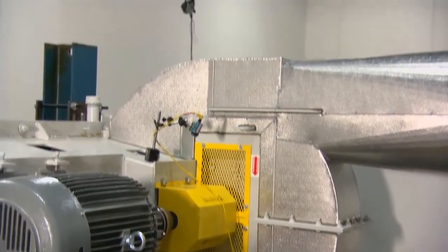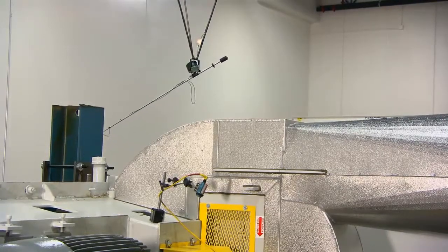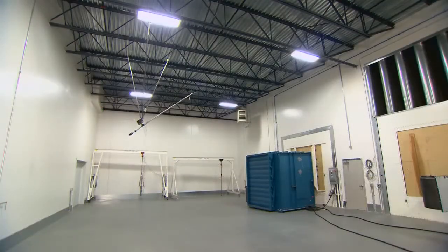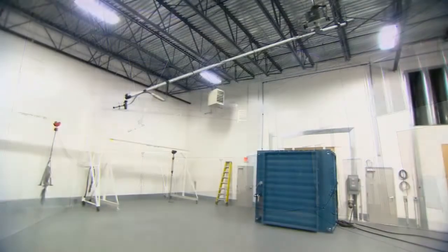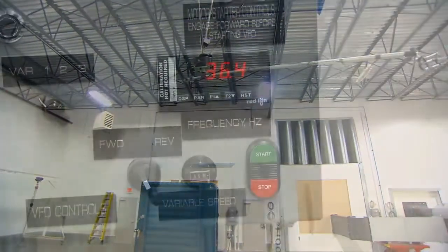It is very analogous to a light bulb. When you have a light bulb, it tells you what the watts of the light bulb is. But when you put that same light bulb in a dark or in a bright environment, the eye perceives it differently. Similarly, when you have sound, you get the sound power, which is a watts type measurement, and then what the human ear hears is sound pressure, which is the perception of the sound power that is being radiated. So the testing that we do in the Twin City Fan laboratory established the true sound power, just like how light power is established in watts.